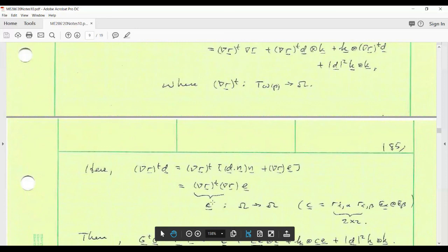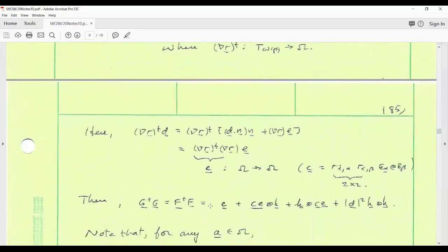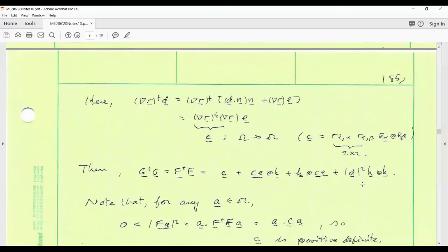We'll call that C, small c, because its structure is exactly the same as the Cauchy-Green deformation, capital C. Here it is in components. You write out grad R, do this operation, and you get this component form. Sum on I from 1 to 3, alpha and beta run from 1 to 2. At the end of the sum on I, you get a 2 by 2 matrix. So that's like a 2 by 2 Cauchy-Green deformation pertaining to the midplane.